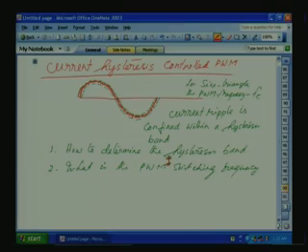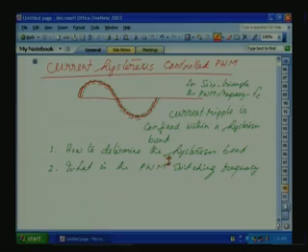So let us take our basic inverter schematic, that is our half bridge configuration, and let us define a hysteresis boundary. Now we are going for a general boundary. This is a sinusoidal reference current and a boundary along the sinusoidal reference. We can also have a DC current and we can design a boundary here, so that the ripple is within this one.